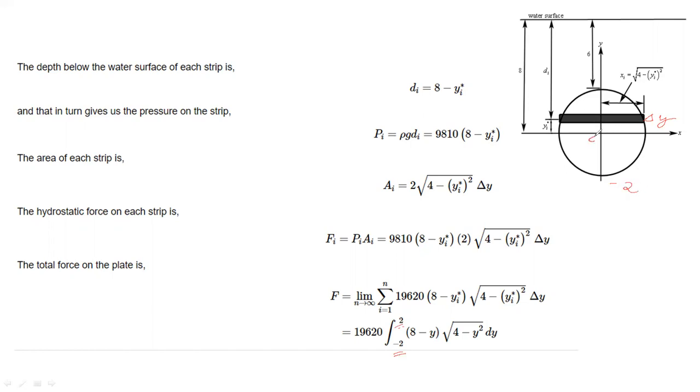And since this is where our Cartesian plane origin is, this is 0 and this is 2. So if we are to sum up all the delta y's here, all the dy's, that will be starting from -2 to 2. So that's the purpose why you have to set up the center of your coordinate axes on the center as well of your regularly shaped area.